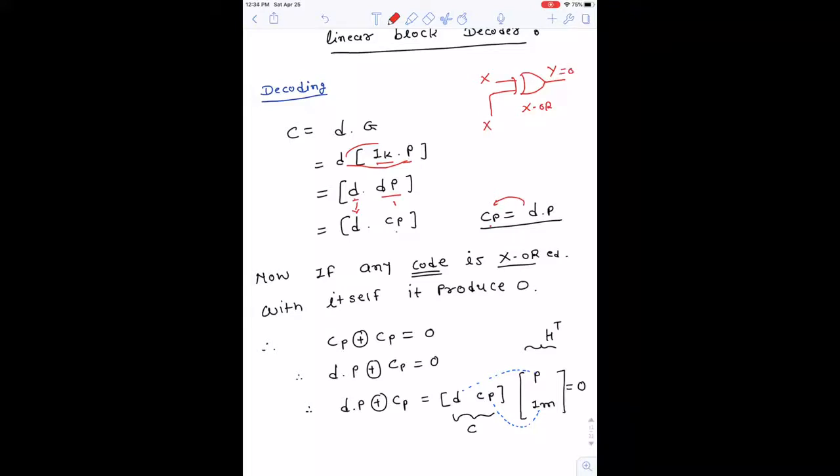But if the input here is different from X, it's the inverter of this, right? So Y is always 1. So if you have a 0 0, then Y would be a 0. The same way, if you have a 1 1, let's say I write here Z, and if I make Z equal to X, maybe a 1 1, you are getting 0, maybe a 0 0, both are similar, then you are getting 0. So if you feed the XOR with the same input, the same bit in both inputs, then you are getting the 0 outcome.